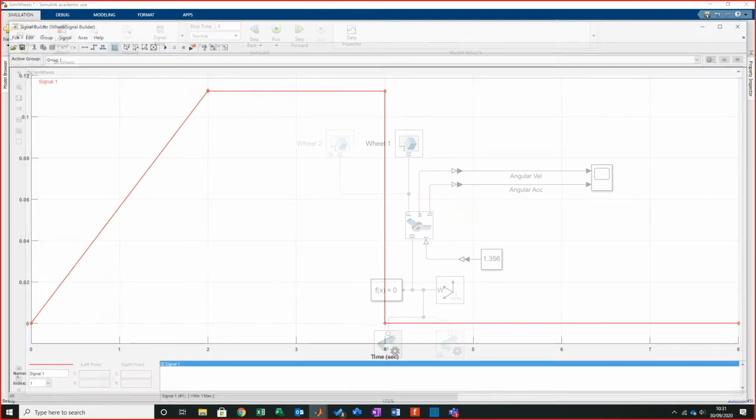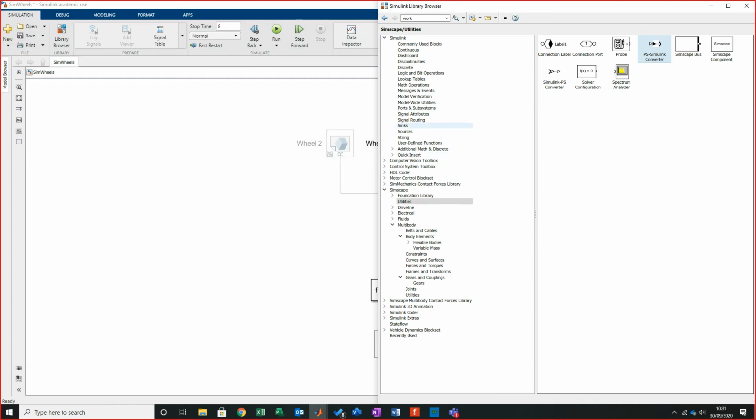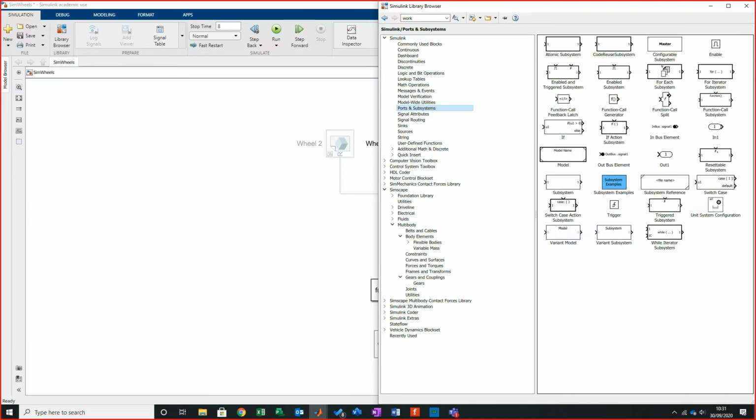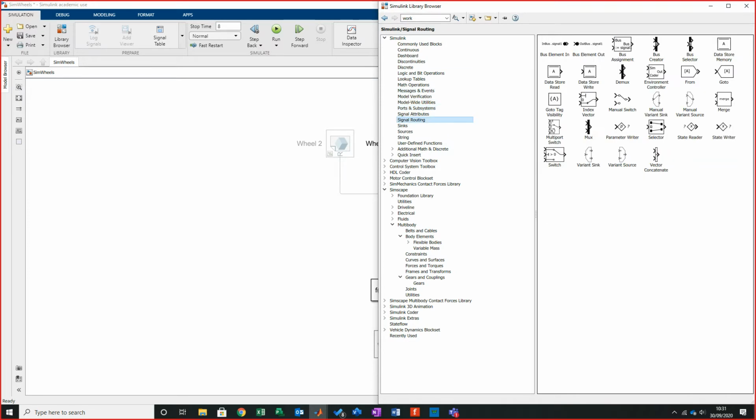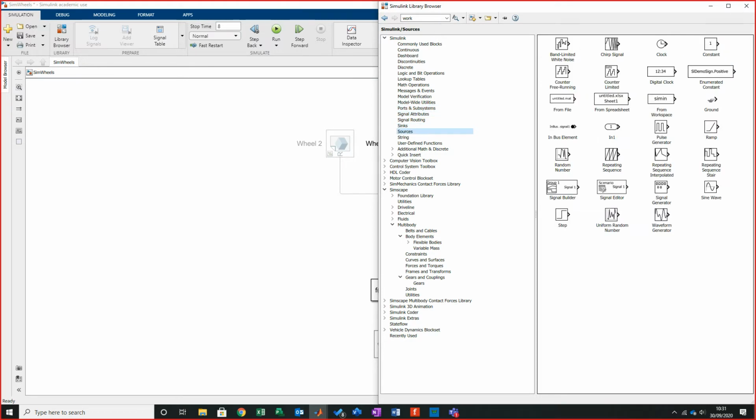So what we're going to do is bring this back, and I'm going to delete that, or rather hide that, or comment that out. The only reason is I think it's good to keep that there as a reference. And if I go through the library, I always manually go through the library. If anybody wants to type it, it is Signal Builder. I go this way so everybody's aware of where everything is. In Sources, apologies, you'll find Signal Builder.